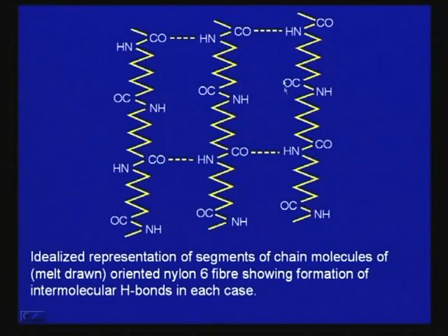So, here you see also the effect of hydrogen bonding on the polymer properties, their melting temperature. The melting temperature is not all. This hydrogen bonding makes them crystalline, makes these polymers stiff, makes these polymers strong. Now, this nylon is so strong, provided the length between two polar functional groups, amide groups, is regulated, then one can get very tough and strong polymer, which is used for making mechanical gears. Mechanical gears are made of this nylon, self lubricating gears. Self lubricating gears are made from these polyamides. Today, sometimes self lubricating gears are also made from ultra high molecular weight polyethylene.